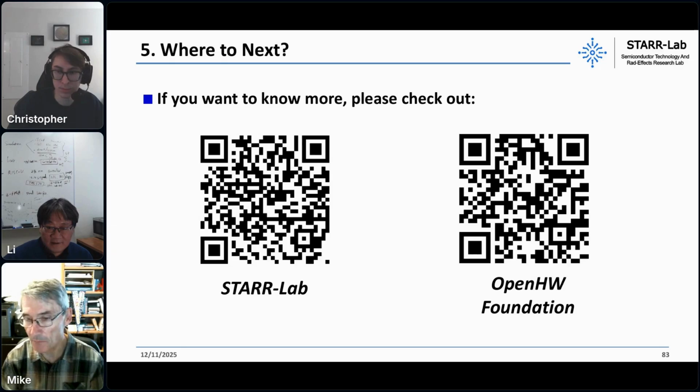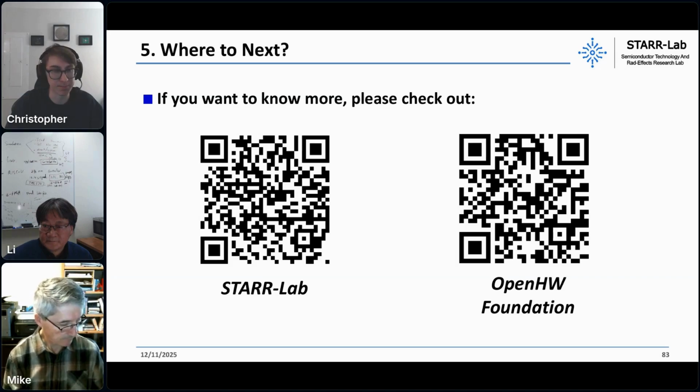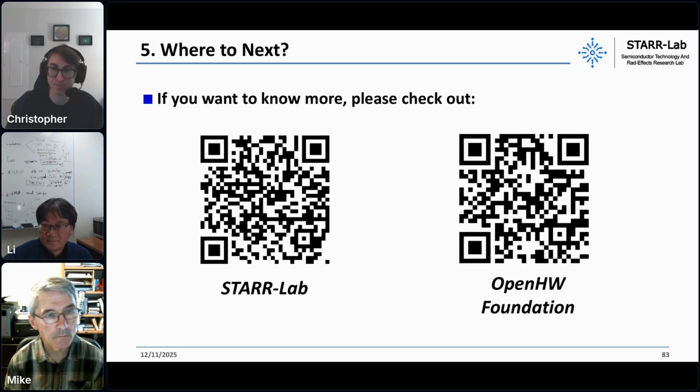One is from Marco. Straight off the bat, are you increasing the supply voltage when you run the StarRISC? Good question. The supply voltage to really any device can affect the soft error rate or the cross-sectional curve. In this case, we run the device at just the nominal VDD supply voltage for this technology. But you are right that if you overvolted it, you would get better soft error rate performance, and if you undervolted it, you would get worse. So for us, we run it right at the nominal voltage. Right, the nominal voltage. Okay, cool.